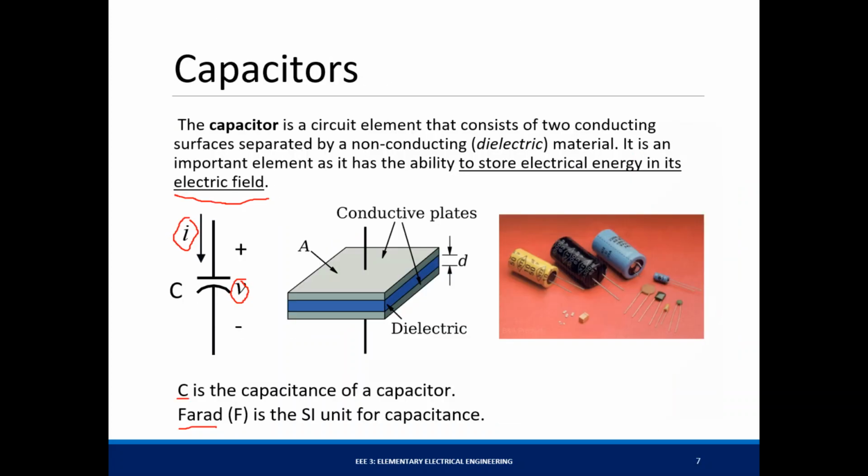Okay. For a capacitor, it's an open circuit. Between these two conductive plates is what we call a dielectric, which is an insulator. So there's no current passing through this region right here since this is an insulator. Okay. So if there's no change in voltage, there's no change in current. Sorry, there's no current going through the capacitor because there's no induced displacement current, as we call it, from this plate to the other plate. But anyway, it's just an open circuit. There's no change in voltage.